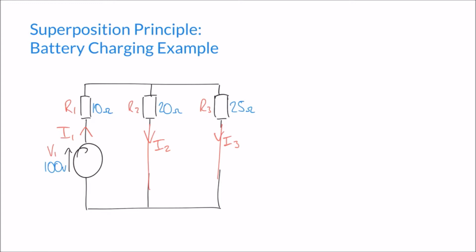To begin with, let's look at the total resistance in our circuit, beginning at the supply and moving through the circuit back to the supply. What we find is that our first resistance, R1, is 10 ohms, and then we reach a point where we split and go through either R2 or through R3, joining together back to the supply.